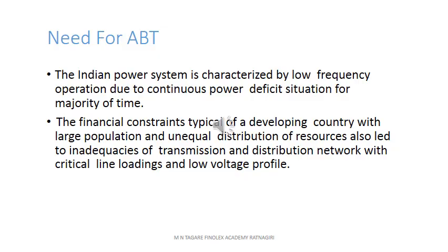Now if the load on the generator increases, what will happen? The moment electrical load increases, the mechanical input is constant. Electrical load change is an instantaneous phenomenon, but changing the prime mover input is a mechanical phenomenon, so it has a larger time constant. The governor will take a little time to understand that electrical load has increased, but electrical load increases in real time. So the generator has less mechanical input than needed.